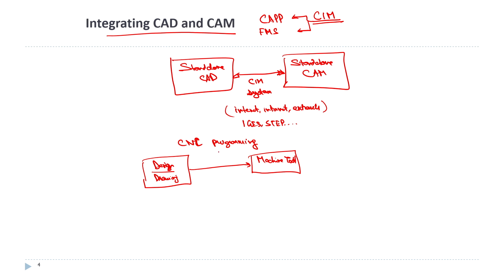So, now not only the neutral file would help us to do it, the post processor also needs to understand something, and it needs to convert the drawing into the final usable format. Now, the geometrical entities of the part must be ordered properly, and the numerical control information must be pushed on separate layers. So, imposing these requirements on the generation of engineering drawing enables the automatic generation of the NC programs.